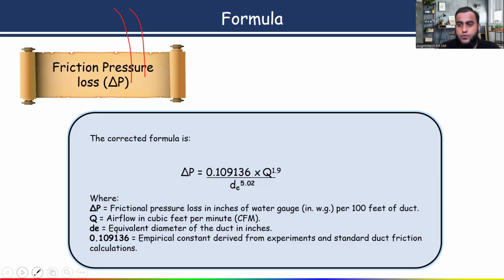Now let's say you are calculating the external static pressure for ductwork, and any fittings are coming, like an elbow or a transition reducer. How will you calculate the external static pressure in an elbow or reducer, or a diffuser grille? As I told you, external static pressure is caused by the ductwork, diffusers and grilles.